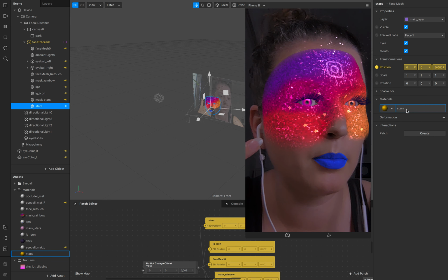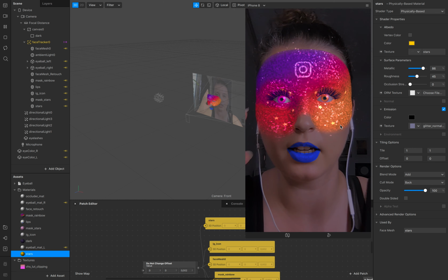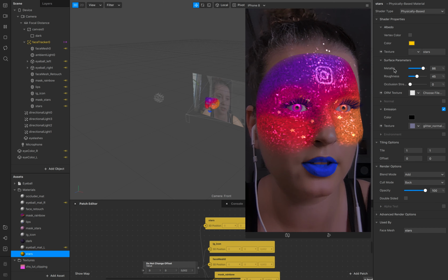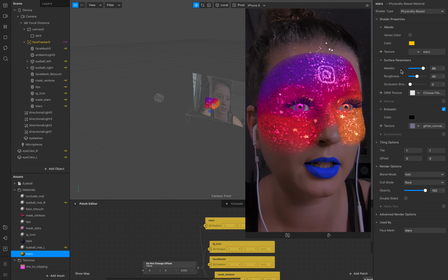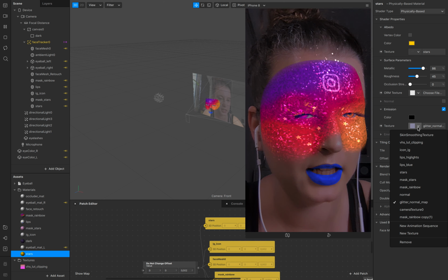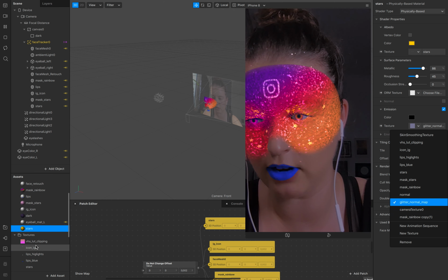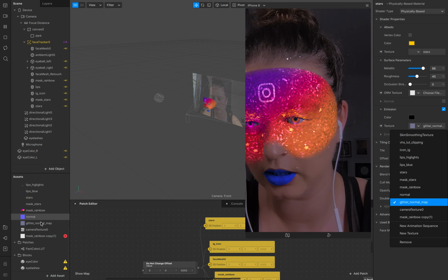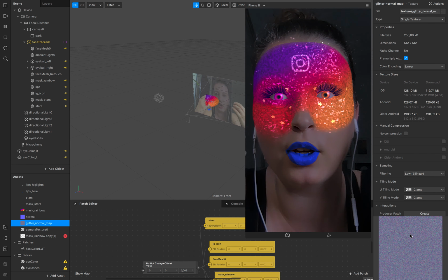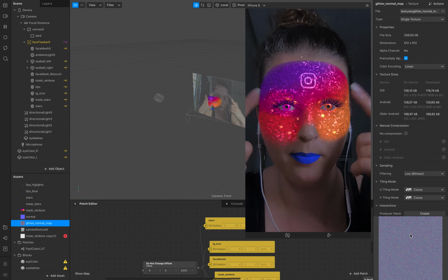And the material is just a physical material. You can also create the glitter effect with physical material, and go just to material, metallic, roughness, and emitter. And I have another glitter map in right here. This one right here. It's a little bit smaller, so that's not so rough like in the example here.